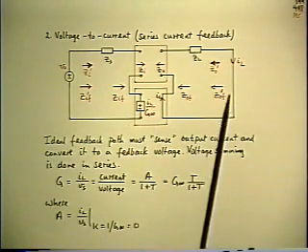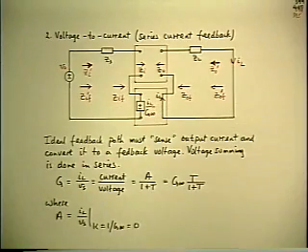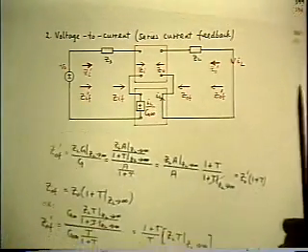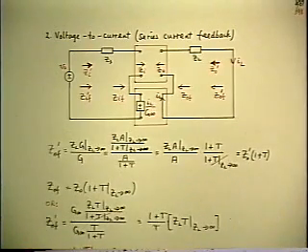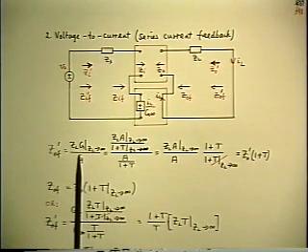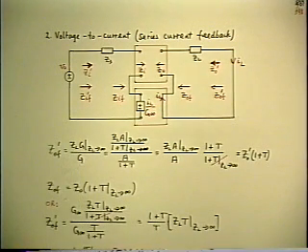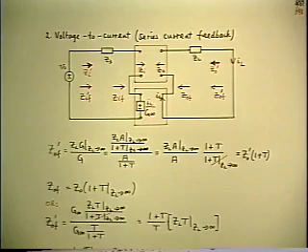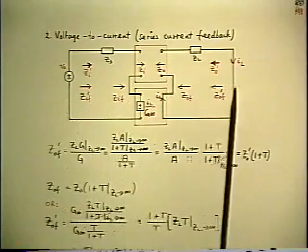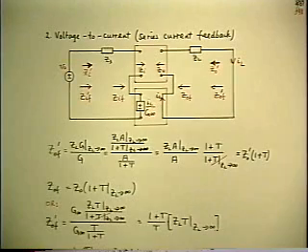So the only difference is the nature of the feedback connection at the output, and now you can use the input and output impedance theorems again to find what the effect of feedback is. We have a little problem at this point though. The output impedance theorem was set up on the assumption that the output signal was a voltage. So actually you need a different form of the theorem if the output signal is a current. But I purposely set up these drawings so that we don't have to go back and rederive a new theorem. We can set it up by direct analogy with what we've done already.